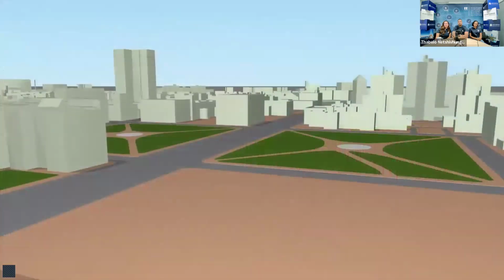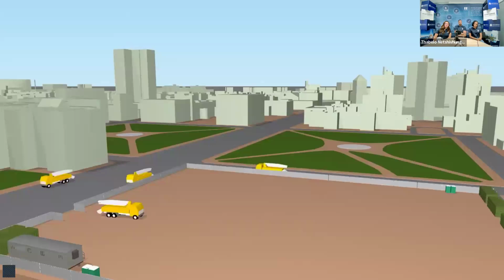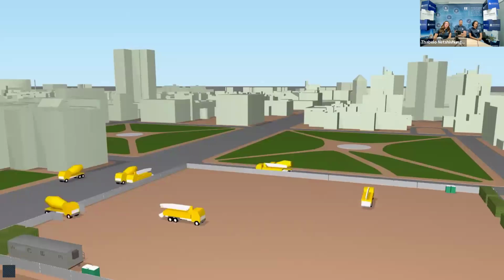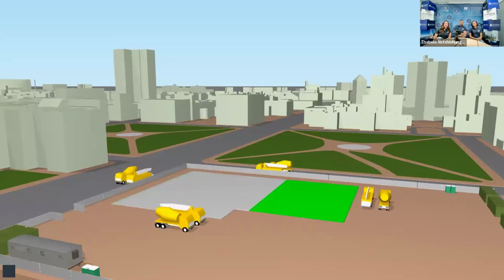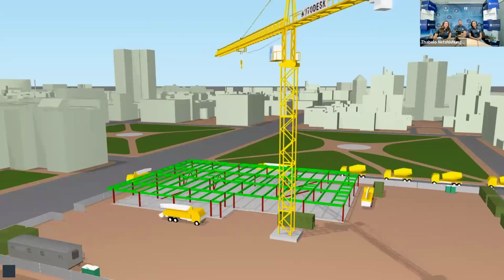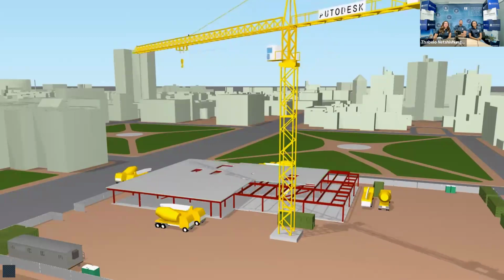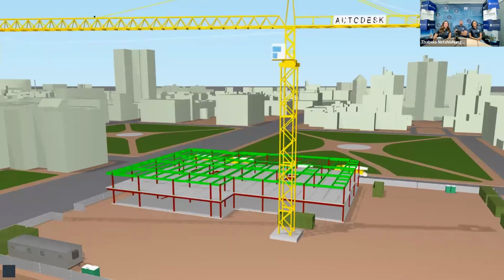This type of analysis can be further augmented to include logistics simulations, creating mock-up scenarios of construction sites to assist in planning and visualizing areas of potential risk. For example, finding optimum positions for site cranes, and ensuring adequate clearance with surrounding buildings, topography, or temporary structures, such as scaffolding. Using the schedule to identify when materials will be delivered to site and where they can be staged, for example, whilst maintaining relevant access routes.